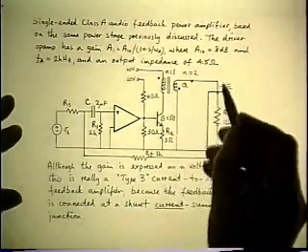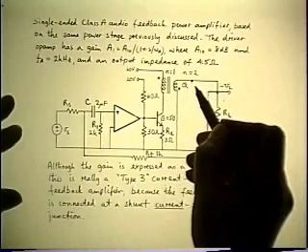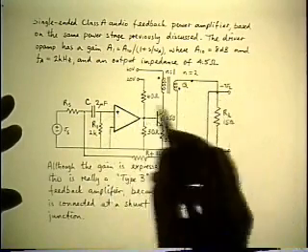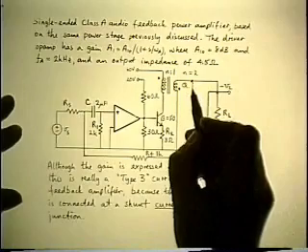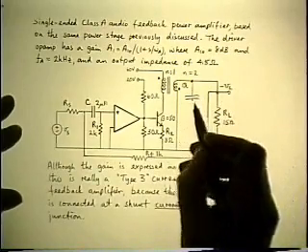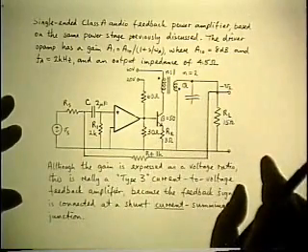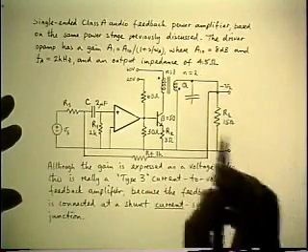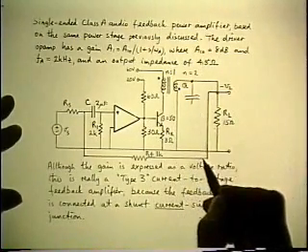In this case, it wouldn't matter because this point is a DC ground anyway. But in general, if it were some other point, all we have to do is put a large blocking capacitor in there. So this separates any problem of upsetting operating point. Now we have to implement a current source.